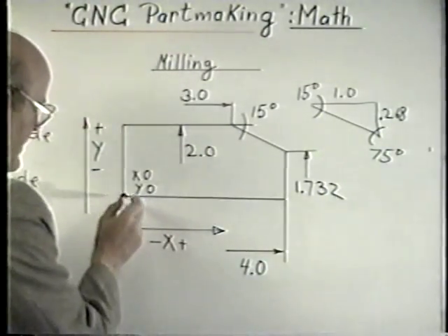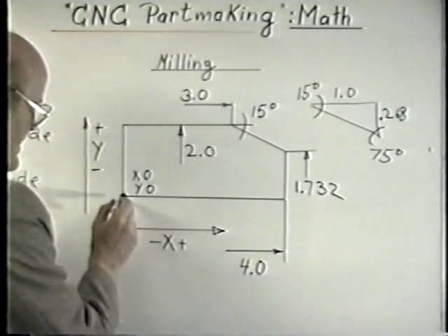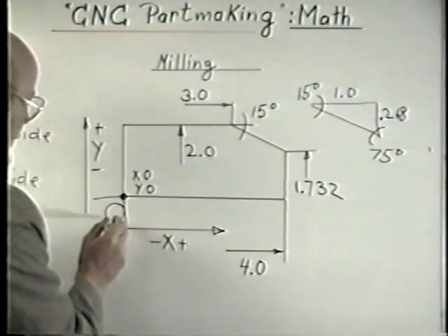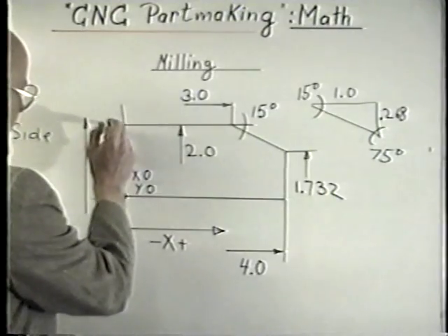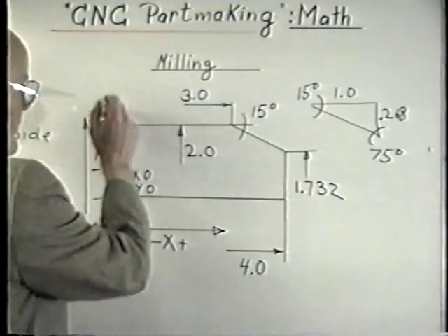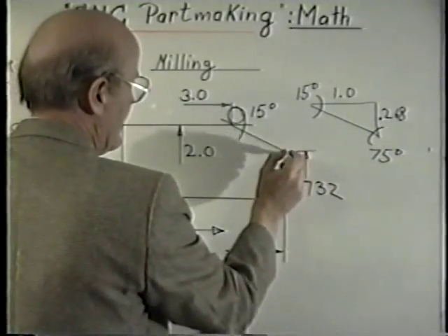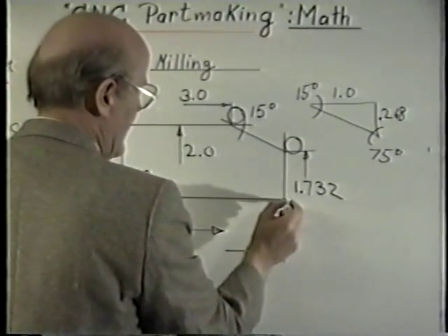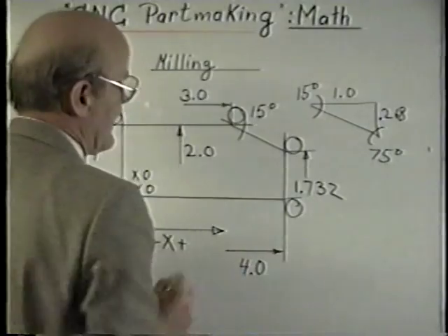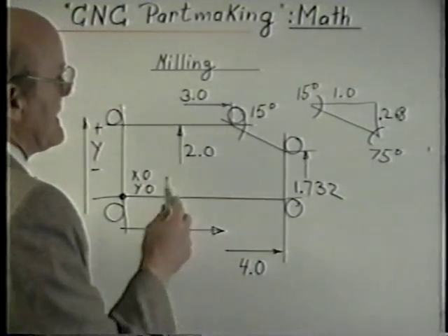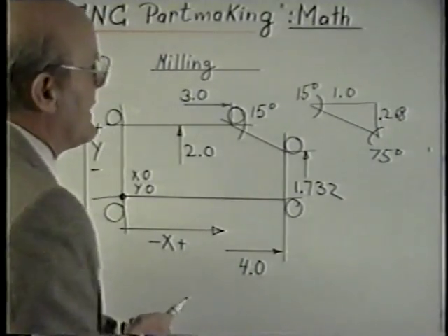And now typically, using cutter compensation properly, I can now put my tool to this position, actually tell my tool to feed to this position right here. Cutter comp will hold it around it, go to this position. I just program the actual part dimensions all the way around my work part. That is the use of math for CNC lathe and CNC mill programming.